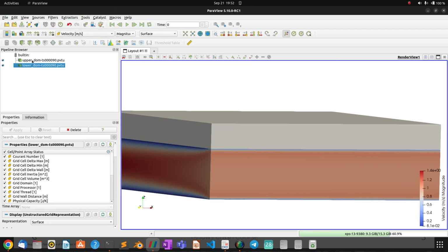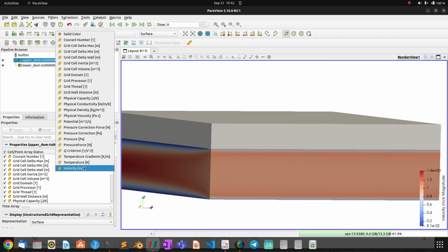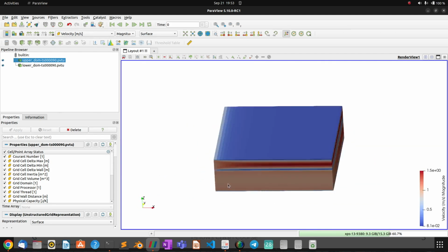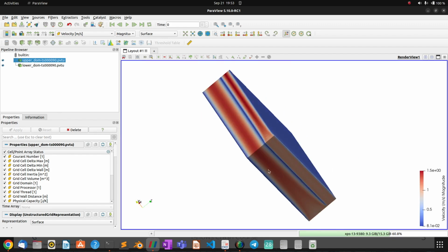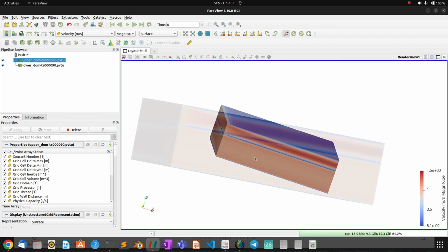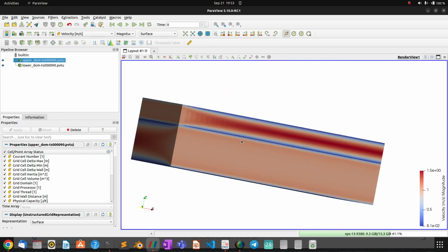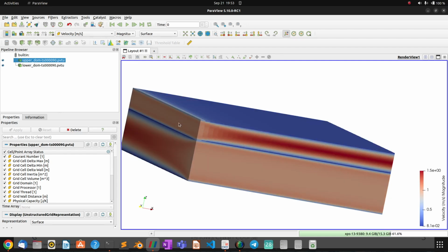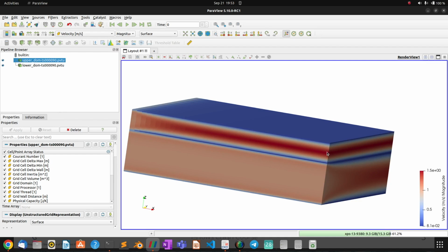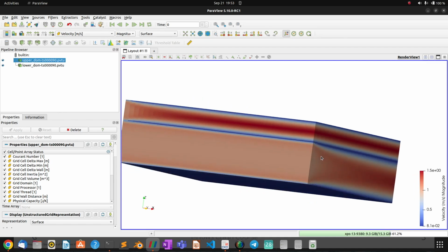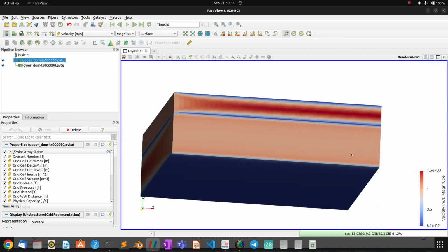But let's say if we want to use surface to prepare for velocity input, and here we want to use velocity also. So yeah, it's kind of interesting, because here you can see already from how the velocity profile is, the flow is fairly laminar in this case. So this is an inlet top hat profile. Then the flow develops in this direction. Then the boundary layer gets a bit thicker because it develops over time, and then towards the end of the domain it is more or less a settled flow state.